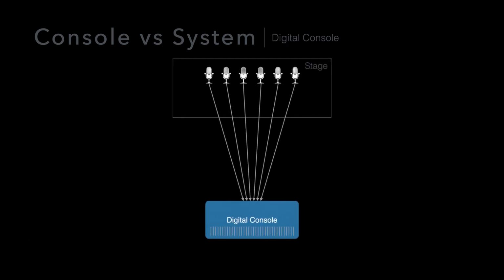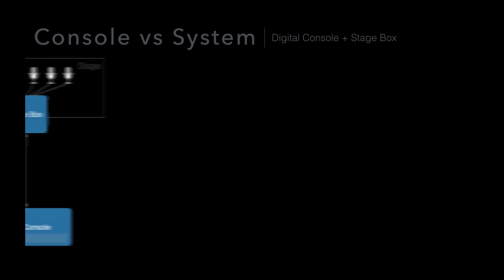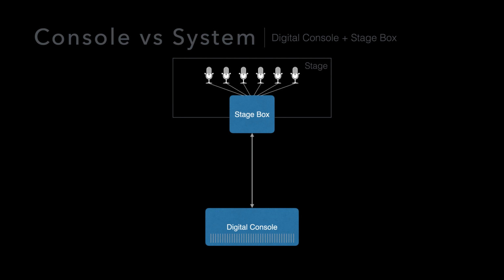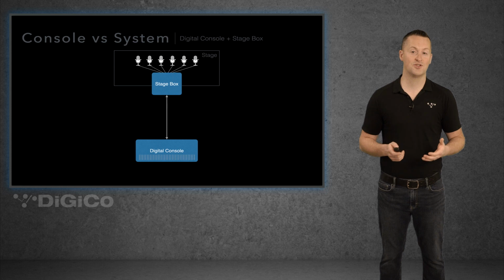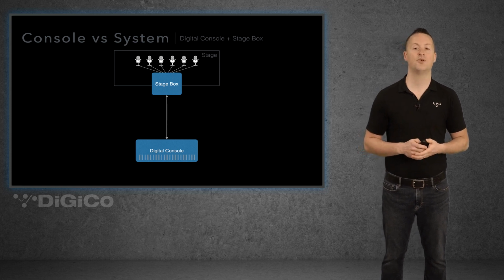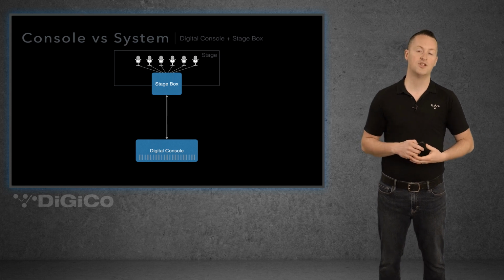All right, so digital consoles, when they first came out, were simply designed to replace that analog console. Use all your existing analog infrastructure, and this is how a lot of them are made today. More recently, you've seen digital stage boxes. Some of them actually have the DSP inside of these, but more commonly, the DSP is inside of the console, and the stage box is just that, a stage box. And then we simply connect those lines on the stage, whether that's floor pockets, wall plates, or directly to the stage box, and that stage box connects to the digital console via Cat5e or Cat6 lines. It may be coax, it may be fiber, depending upon the infrastructure. This makes it very easy to install into retrofit installations because it's a very simple cabling run from the digital console to the equipment room or to the stage.